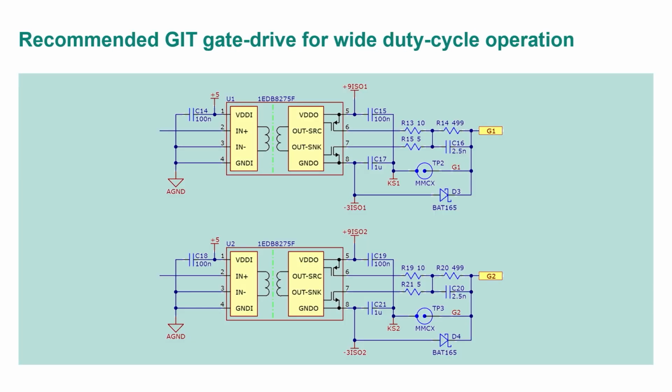Here's an example showing the gate drive circuit that we use in our reference designs. This is a gate driver that has a fast clamp so that even without power, we can make sure to keep the gate to Kelvin source here clamped. And I have the asymmetric capacitors I just recommended. I have the RC network. I have a nice +9 here and a -3.